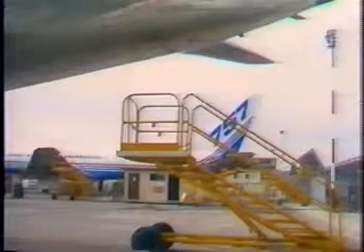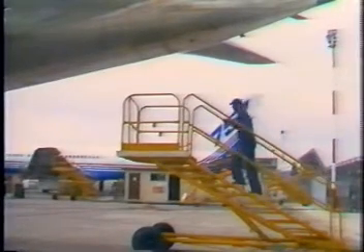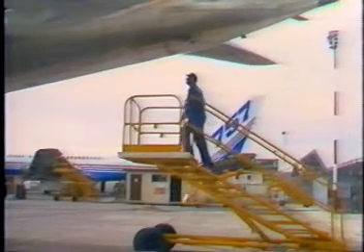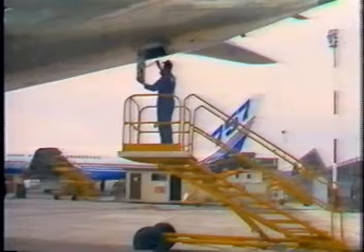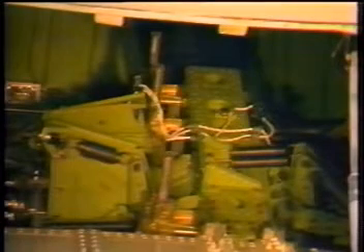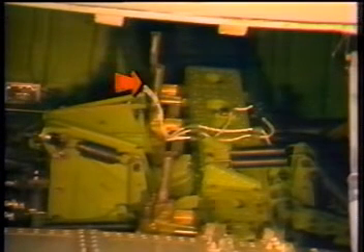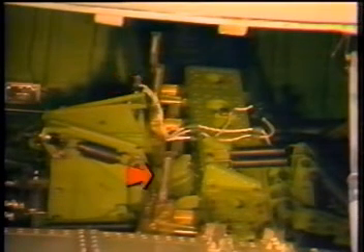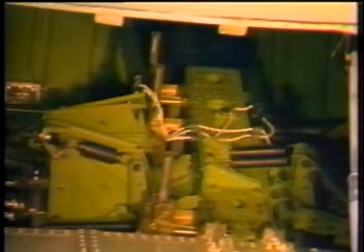The three elevator autopilot servos are located in the tail section. Access is through the elevator control access door forward of the APU access door. The left autopilot servo is uppermost with the center and right servo below, mounted on the torque box. Components on these servos are the same as on the LCAs.